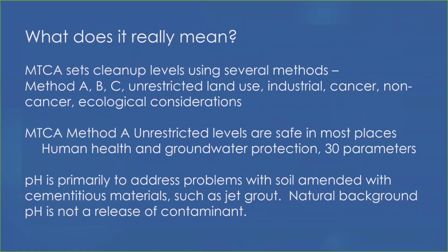So the Method A unrestricted contaminant limits account for the highest human health and drinking water protections. It does set a cleanup level for about 30 of the most common contaminants that are out there. And it can work if ecological considerations are not significant. If ecological considerations are apparent, you know, you're placing materials in an endangered species habitat or something along those lines, you would have to adjust the contaminant concentrations down to be protective of those ecological receptors. And there are tools within the MTCA rule to figure that out.